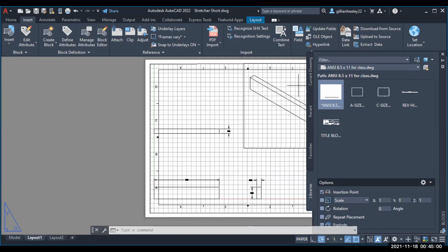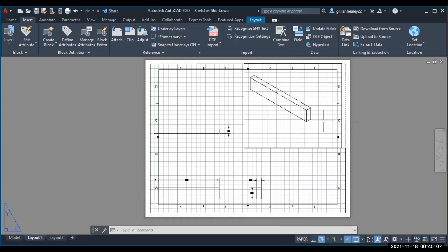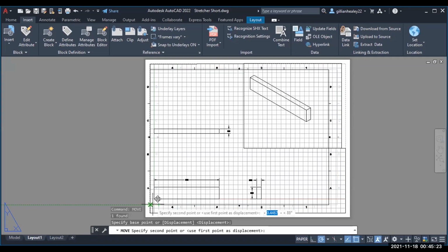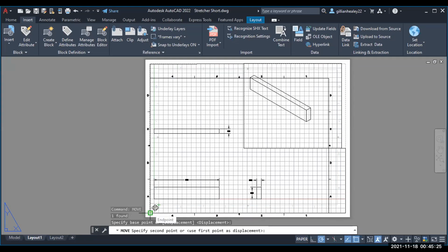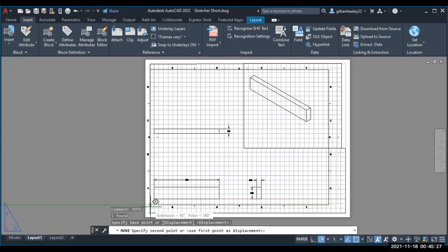So close this menu, the X. Now you can manipulate it however you want, because now you can move it, select the correct base point that you want to use, and you can scale it with that. It was coming in with a base point that probably wasn't very useful. See the base point? It's in the bottom left there. So that's why drop it in and then adjust it as needed and select your base point for scaling and for moving.